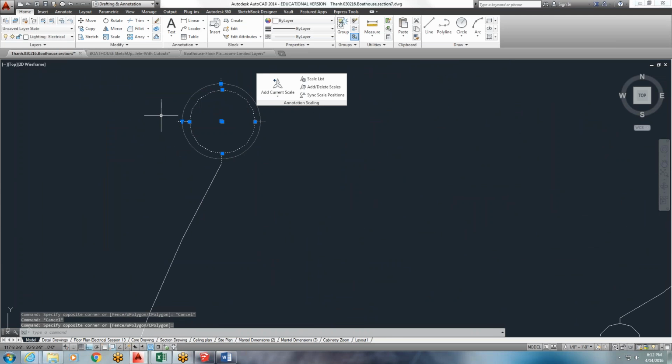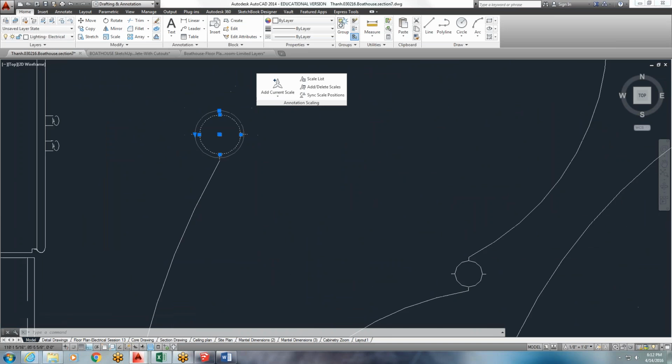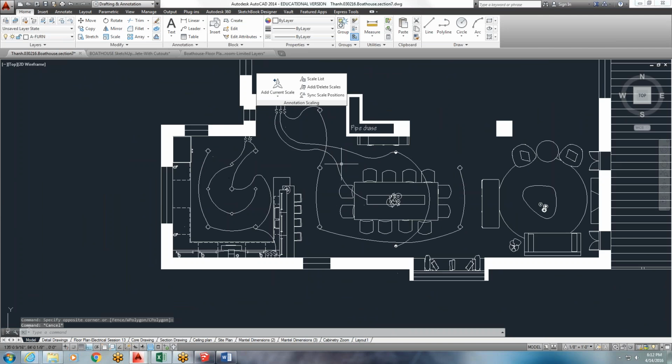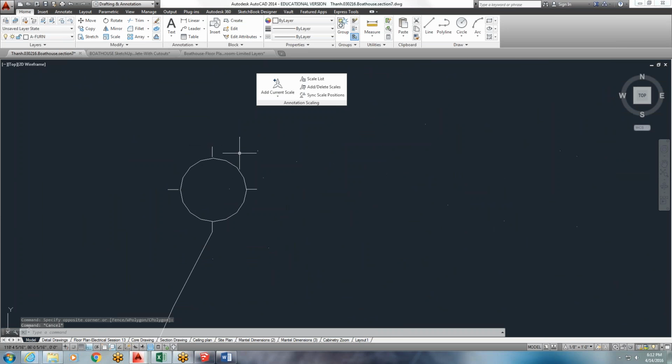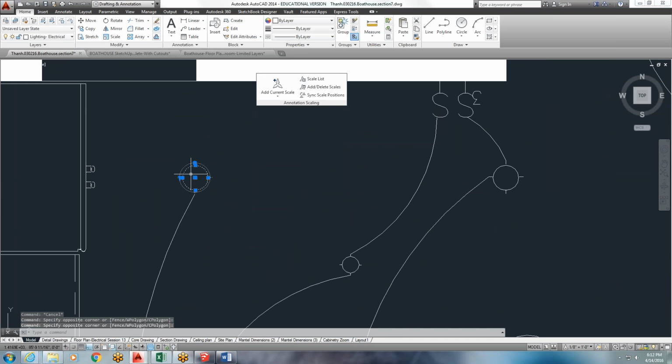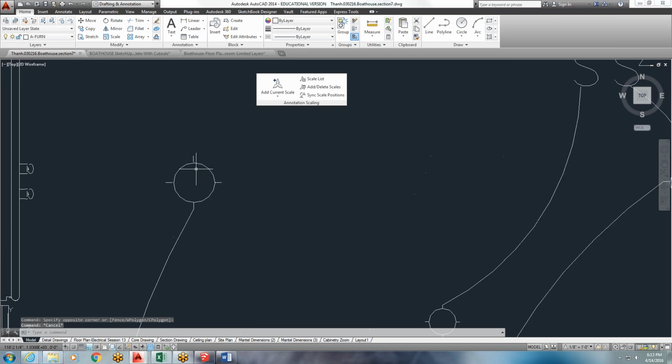I've arrayed the little stems around the circle and it's showing up as double pieces, okay? Once you make something a block or even an array where it has this weird circle, and a student sent me, it was actually Matt, sent me a drawing this week of his array and he said, I can't trim it. And you can only trim an array if you explode the array. So there'll be some exploding that goes on if you try to array some of these.